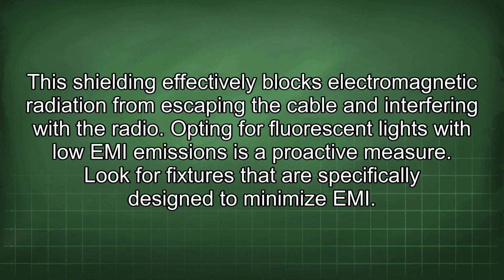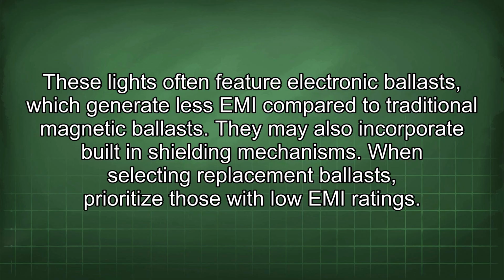Opting for fluorescent lights with lower EMI emissions is a proactive measure. Look for fixtures that are specifically designed to minimize EMI. These lights often feature electronic ballasts which generate less EMI compared to traditional magnetic ballasts. They may also incorporate built-in shielding mechanisms.